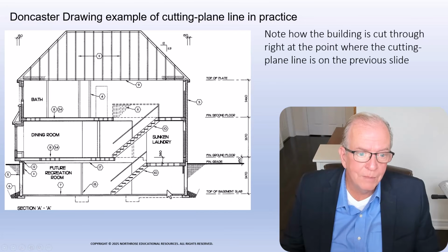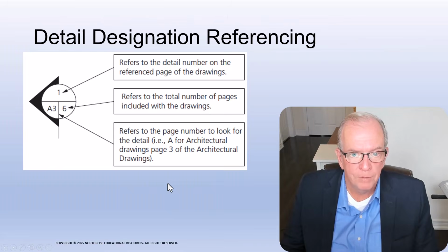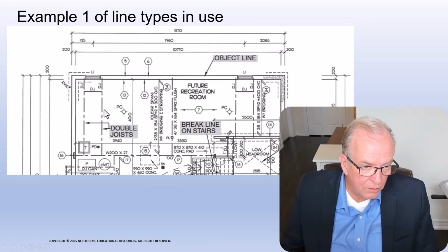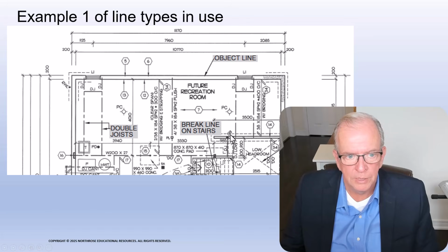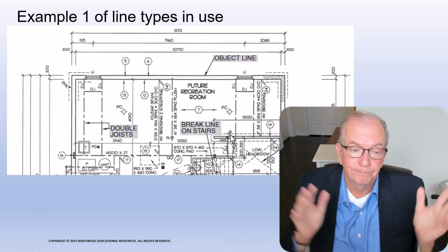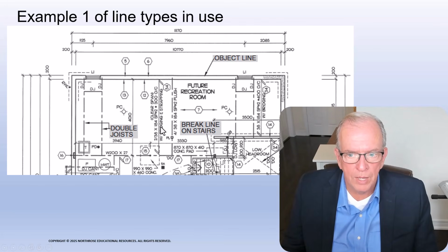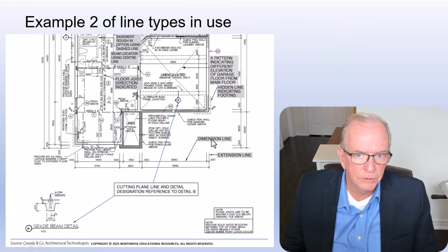You get maybe a 6'6" ceiling or a 6'2" ceiling, whatever that may be, right? So that's giving you sort of that indication. Here, this is the center lines, but because of the abbreviation, I know they're double joists. The DJ refers to double joists, right? So it might say TJ, okay, that would be the center line for triple joists. That's how that typically spells out, right?